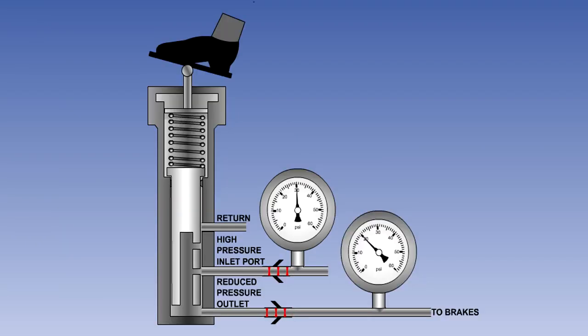A brake control valve, or metering valve, is essentially a variable pressure reducing valve, which controls pressure in the brake system according to the position of the pilot's brake pedals or auto brake selections as required.